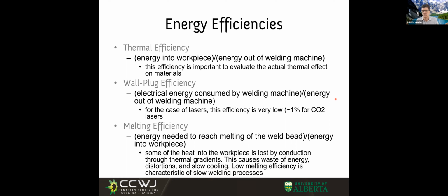But of course, the weld pool ends up being hotter than melting, and the plate ends up sucking up quite a bit of heat. So melting efficiency is a concept that says of all the energy you actually did put into the plate, how much did you use for melting?